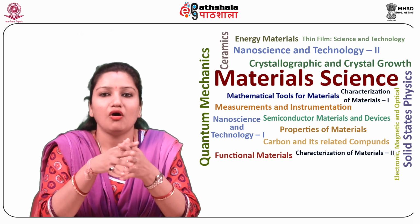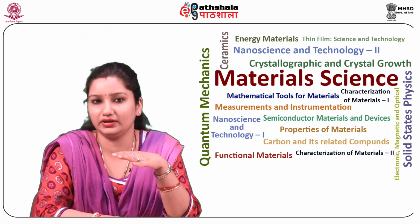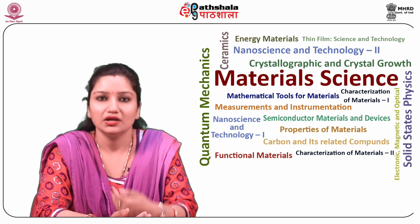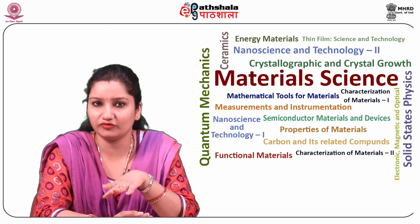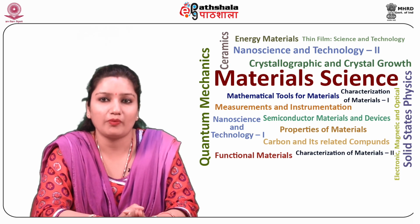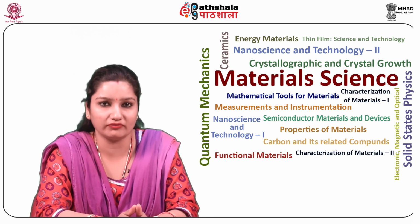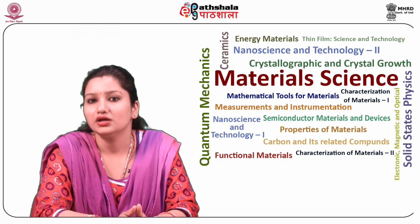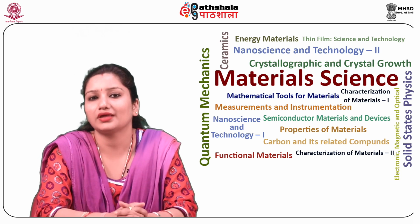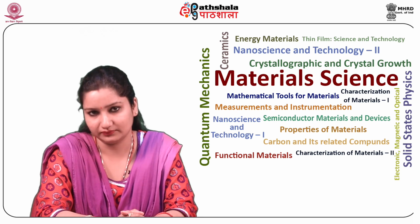This exposure alters the solubility in the developer of the exposed areas relative to the unexposed areas. If the resist prints in the negative tone, the exposed areas are hardened, whereas positive tone resists are made more soluble in the developer solvent by the exposure. The changes in the exposed areas are due to some chemical reactions brought about by the absorbed radiation.